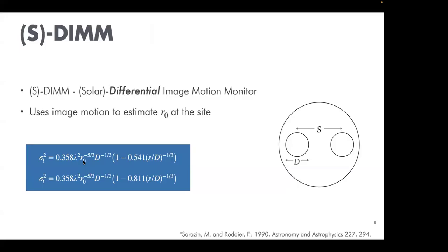Oh, you don't use centroiding. You have different algorithms for estimating the image motion. The two main ones that we tested: one is called sum of absolute differences, where you have, say, an n by n image. You always need a reference image, so you find the image motion of image 2 with respect to image 1. If you have an n by n image, you choose the central m by m of the second image and literally slide it across the first image. It's like a correlation basically.